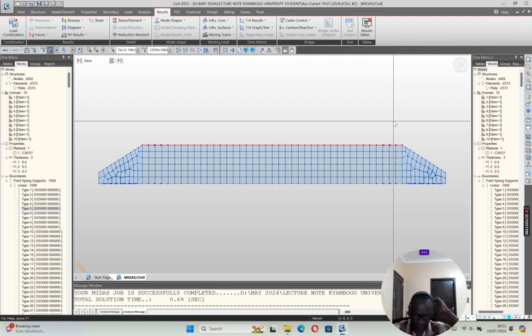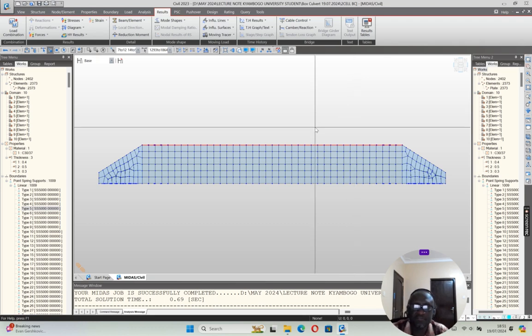The vertical pressure is 0.5 multiplied by 20. Let's say the unit weight is 20. So 0.5 by 20, I would get 10 kilonewton per square meter across. I assume that it is uniform 0.5, though it would be trapezoidal, maybe lesser towards the end, but for purposes of demonstration and understanding, I will leave it at that.